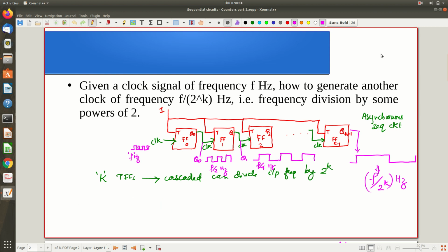So this one is your asynchronous counter, and another name for it is ripple counter. Why are we calling it so? Because of that rippling effect, the delay involved. Every flip flop can work only after finishing the working of the previous one. Otherwise, if it works immediately before that, it will go to something different. So that is our transient state. In between, something different can happen.